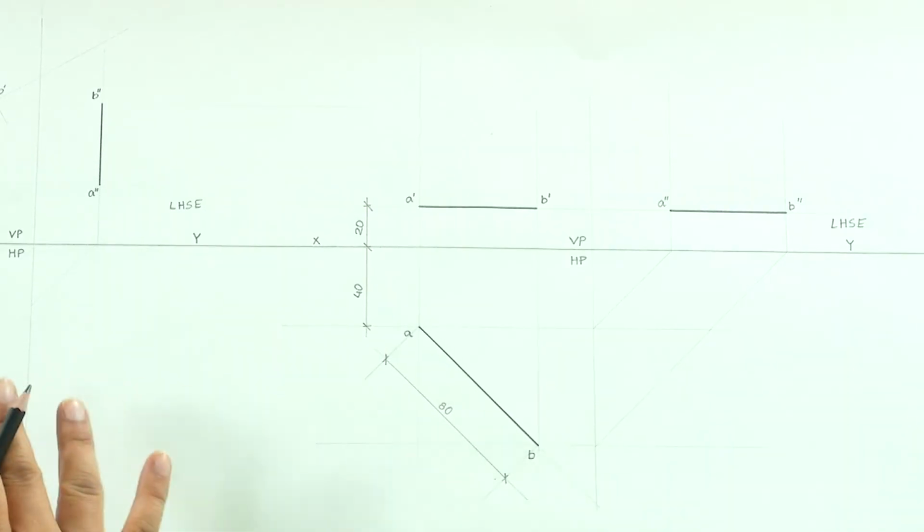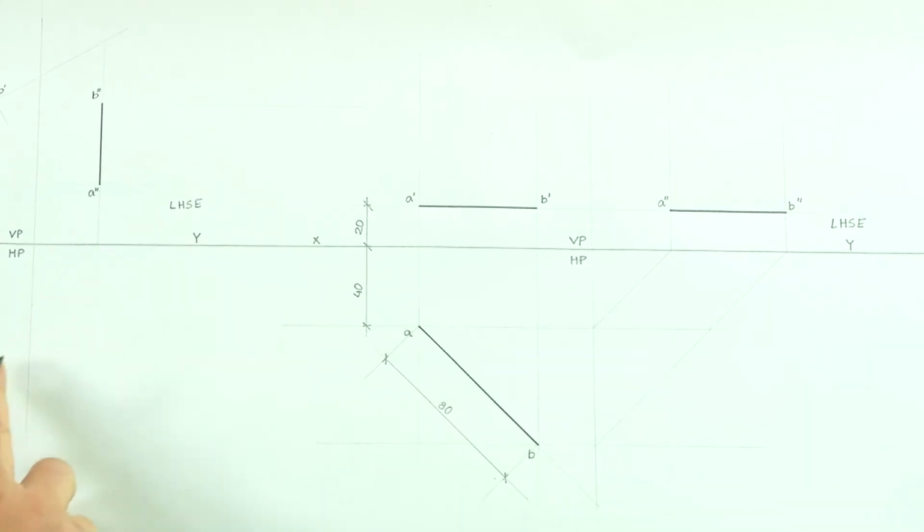Another word of caution is I am familiar with how to draw, so I can directly darken the lines here. Do not copy me here. You should always make the entire drawing very light, almost as dark as the projection lines, and then gradually start darkening it from light to dark. The darkest lines should be drawn last, so that they do not smudge. To come up to this level where we can directly darken it, you have to have a lot of practice, and after practice, of course, it will be much faster, but until then draw it all in light and then gradually darken it.